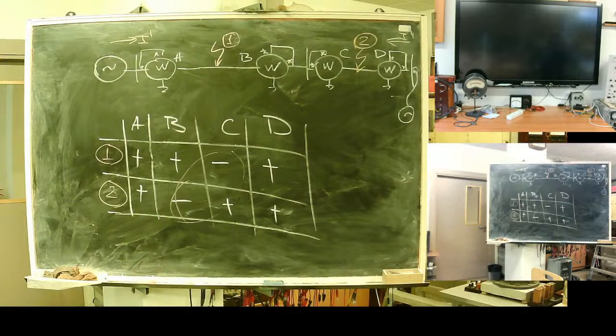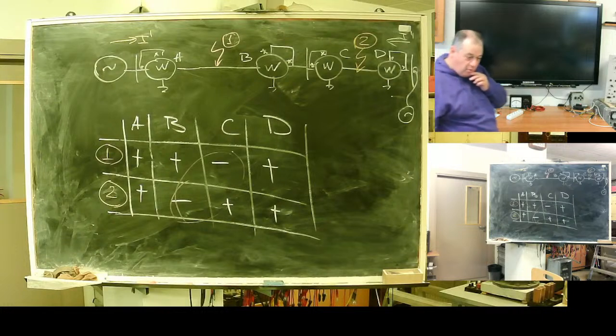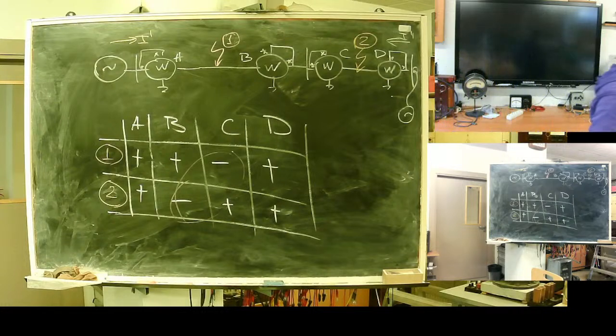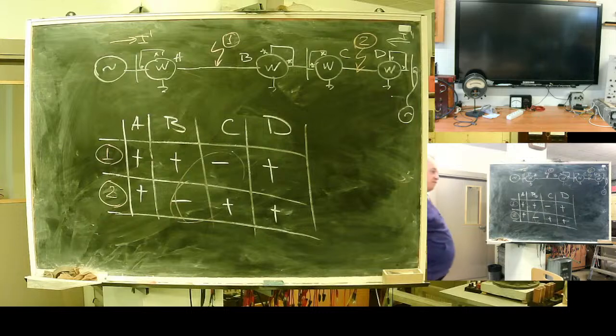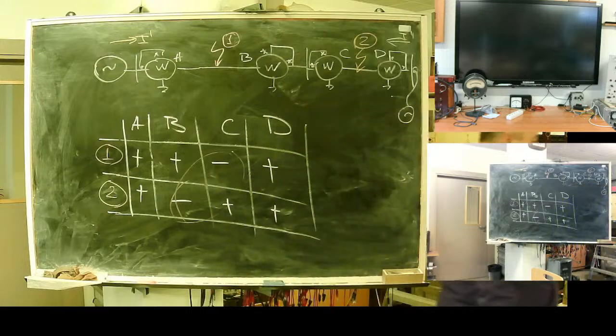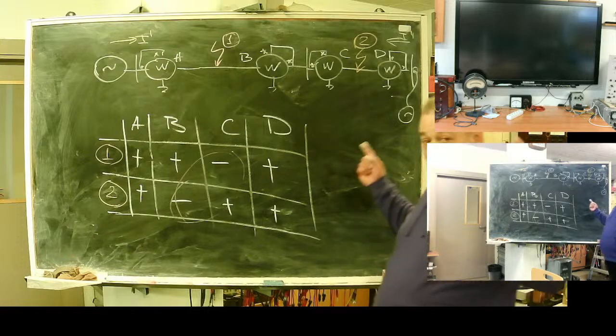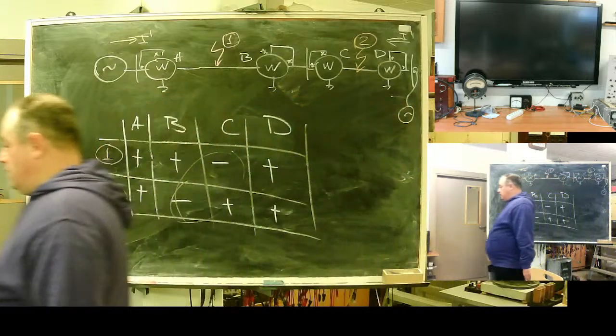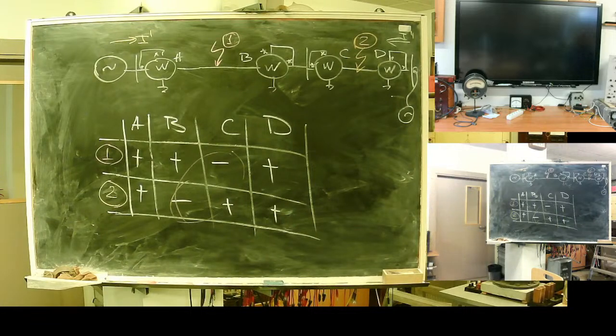If I equip my relay with power flow or power direction function, it appears that it can solve my problem. With discriminate operation on two-side powered line. Yeah?